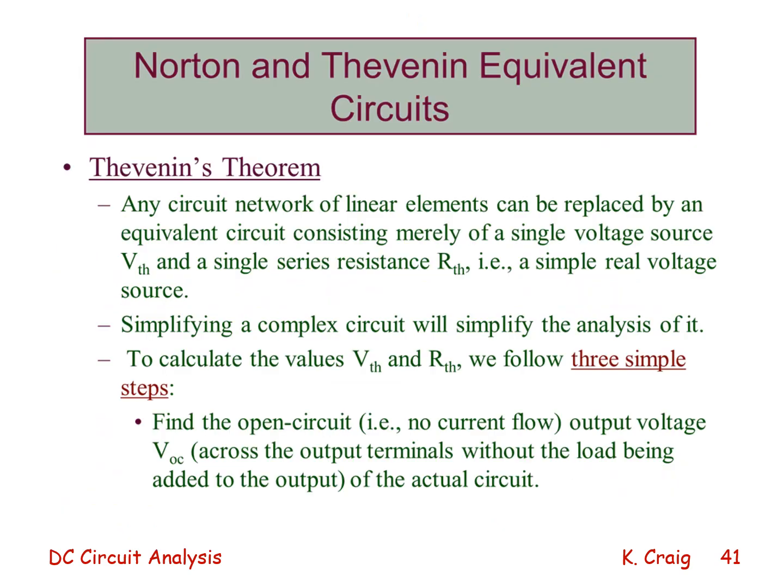Let's talk more formally about Norton and Thevenin equivalent circuits. Thevenin's theorem says that any circuit network of linear elements can be replaced by an equivalent circuit consisting merely of a single voltage source, V Thevenin, and a single series resistance, R Thevenin, or single series impedance.